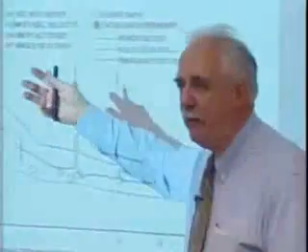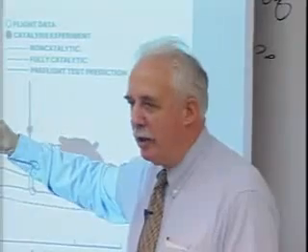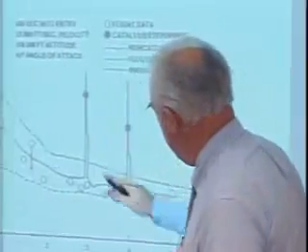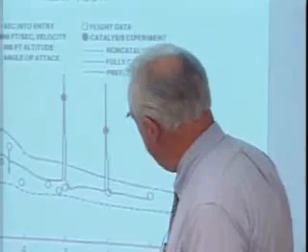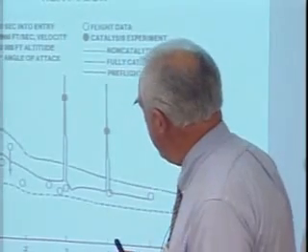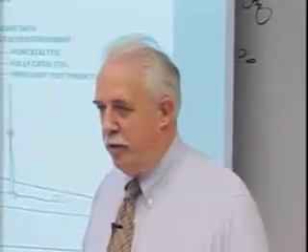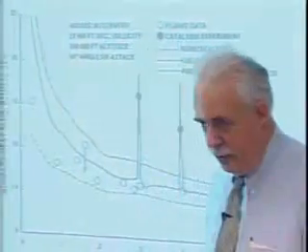Same thing as before, only I eased it by showing temperature instead of heat flux, okay? The surface catalysis is the predominant factor. Now there's some rambling in the data here depending on particular location, etc. Okay, but our friends at Ames developed a catalytic coating, and they coated tiles. And they said, we're going to demonstrate surface catalysis. So they put these tiles at these particular locations.